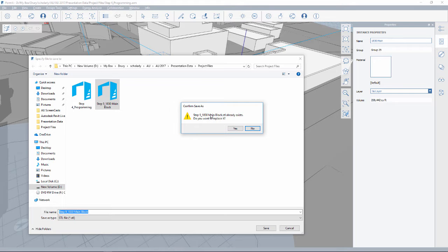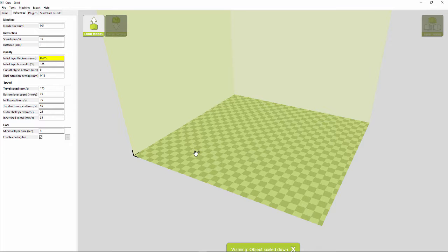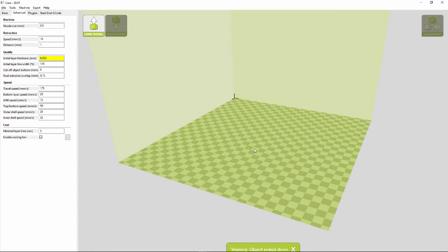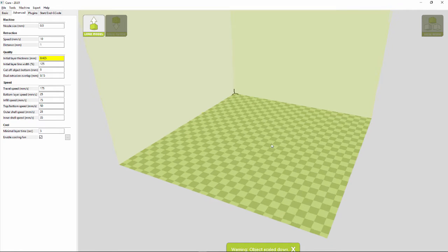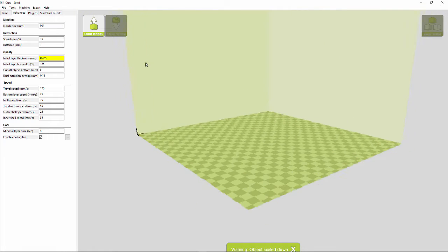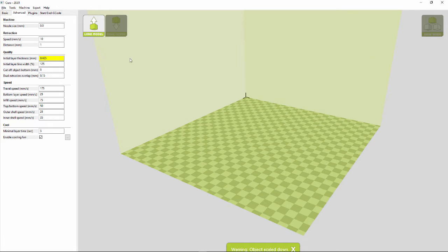And again, naming it with the street address really helps keep all these organized, because once you go into 3D printing, often you need to print these individual buildings one at a time. It's not any faster to group them all on the plate. It might be a little less labor in terms of starting and stopping the printer, but the print time will be exactly the same. And as I often tell our students with 3D printing, if I try and group 10 buildings on here, if one fails, typically they all fail. So one at a time is a pretty safe way to go about it.